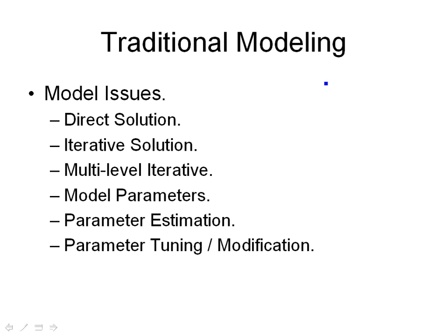That's the innermost iterative solution. And that problem itself is a mathematically very challenging problem. There's this Rachford-Rice contest, and again, people like Nicholson and Zick and a few others have been able to solve the challenge of that to a level that you can guarantee essentially any flash calculation with any set of K values and any composition is solved. That's the innermost loop. And then you've got the outer loop, which is an iteration on getting the fugacities of all the components in both phases to be equal.